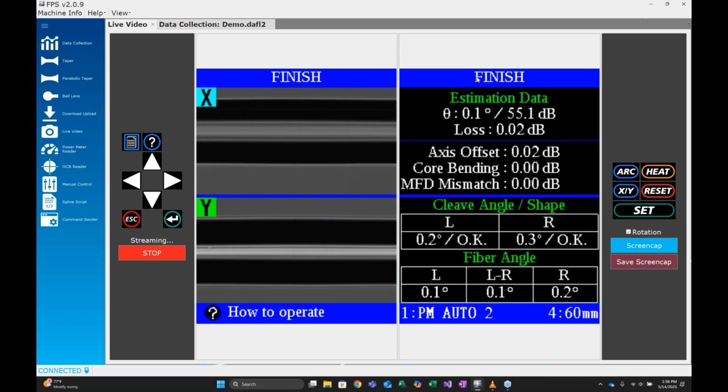But if you're in the standard state, like splicing a regular single mode 125 micron fiber with a 1 millimeter electrode gap, you should not see the electrodes in the field of view. If you do see that, that's an alignment problem, and the splicer most likely needs to be sent in to be adjusted. However, I would say just really double check and make sure there aren't any settings that could be causing the electrodes to be seen by the camera.